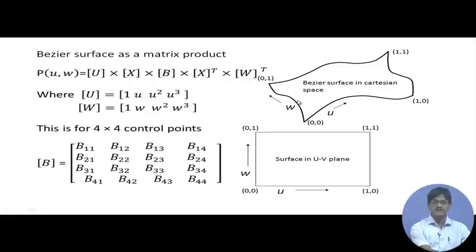So, at intermediate positions also there are lines which are called isoparametric lines, along which the other parameter which is mentioned here as w will remain constant and u can be increased so as to produce a curve right from this side to that side, u varying, but w remaining constant, and that line being known as an isoparametric line.